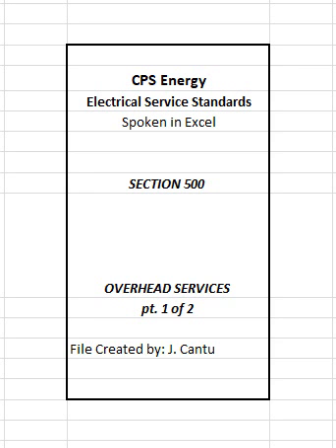1. On service drops such as for residences and small commercial occupancies, a clamp-on type eye-bolt for service masts, or a screw-type eye-bolt for wood structures may be used. CPS Energy installs the anchor during the service drop installation. Customer shall furnish the anchors if the CPS Energy standard type anchor cannot be used.